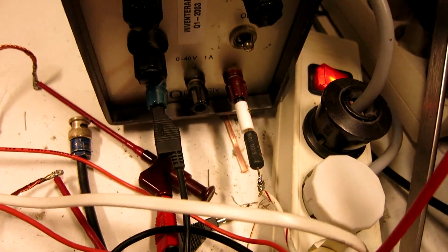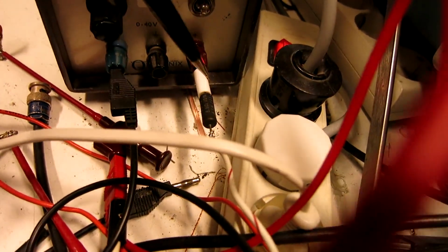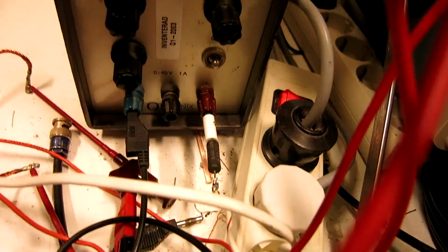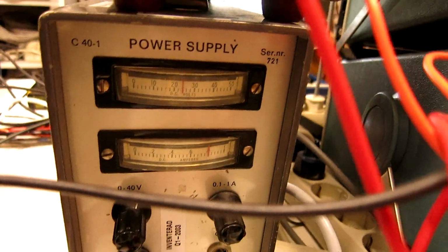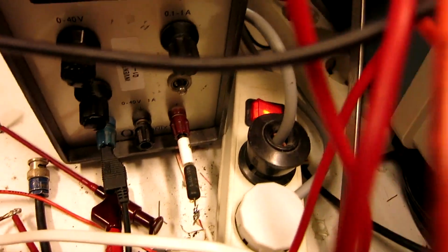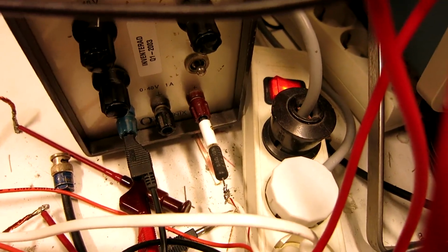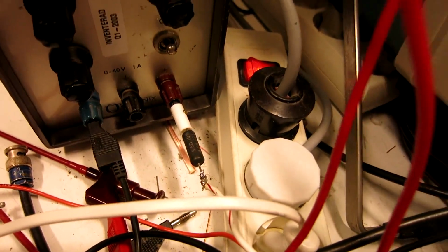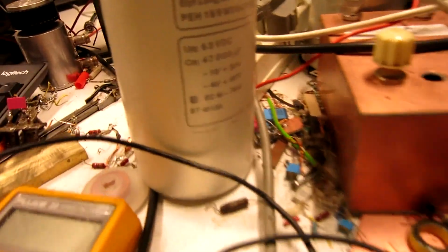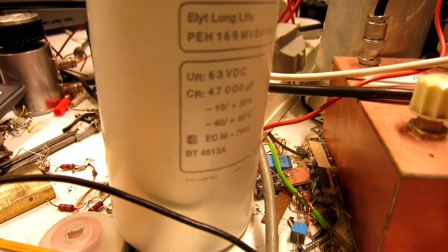Well, a simple error. I had forgotten this resistor here on the power supply. It's 5.5 ohm and the current is 0.8 amps. So it is a considerable voltage drop. I added it quite some time ago to remove low frequency noise on the power supply, because that resistor operates together with this capacitor, 47,000 microfarads.